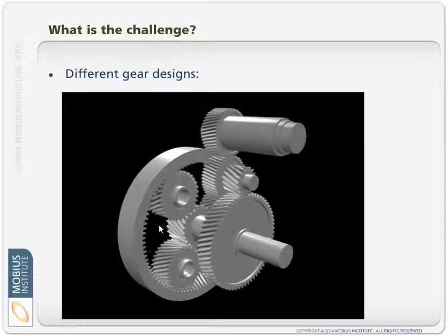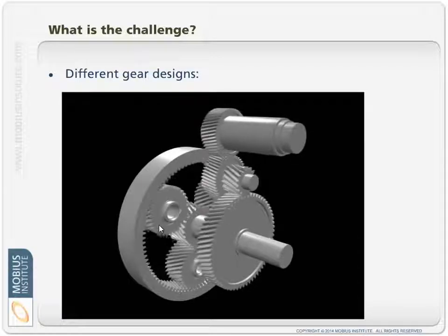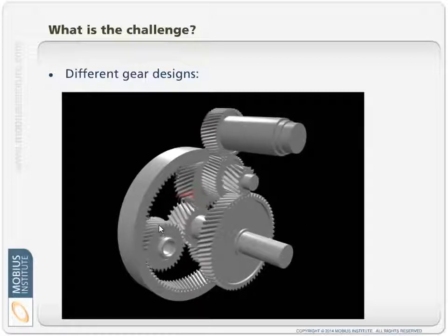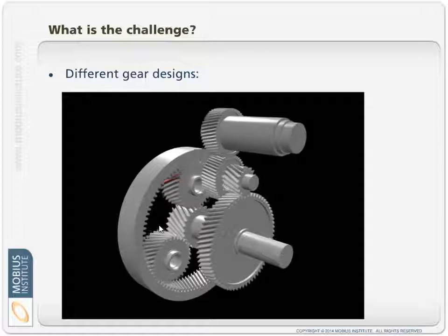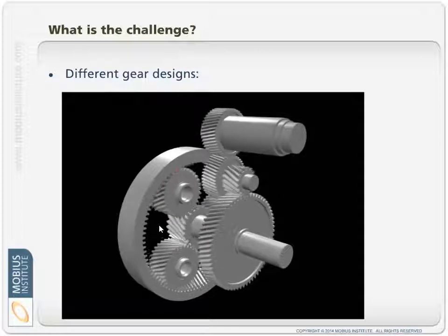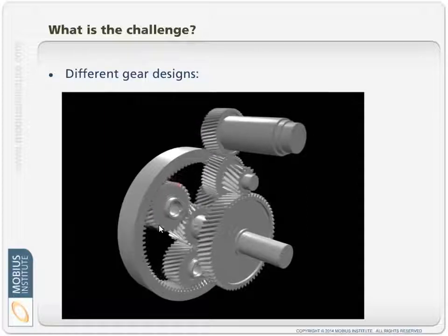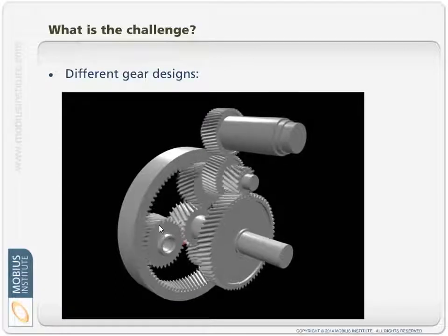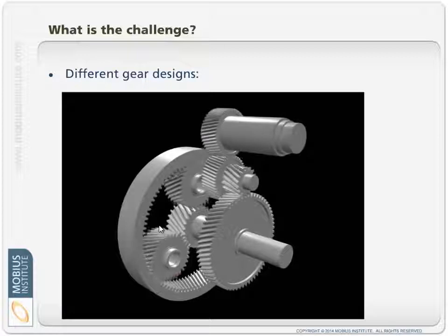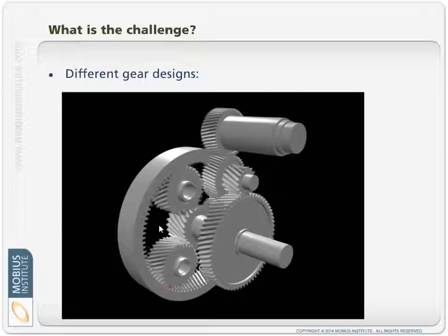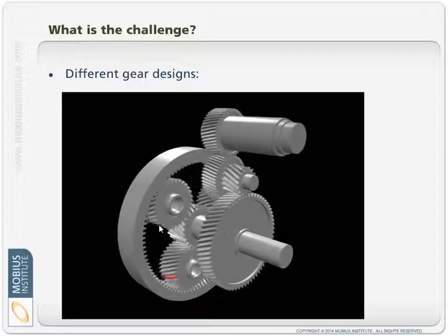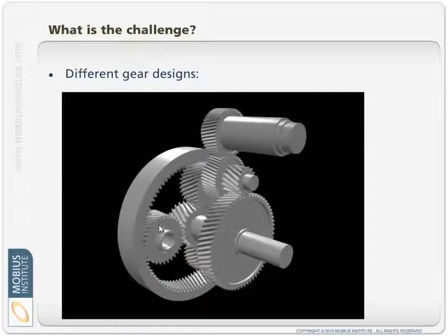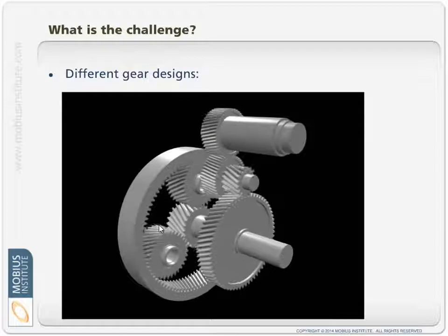You'd prefer not to, but in this particular instance, with a planetary gearbox in a wind turbine, you may not be able to mount as many accelerometers as you might like. In a case like this, you are most likely going to be permanently mounting the accelerometers, and probably permanently monitoring the system as well. But if you understand the design, and you understand all the issues related to detecting gear faults, then you can make the appropriate choices.